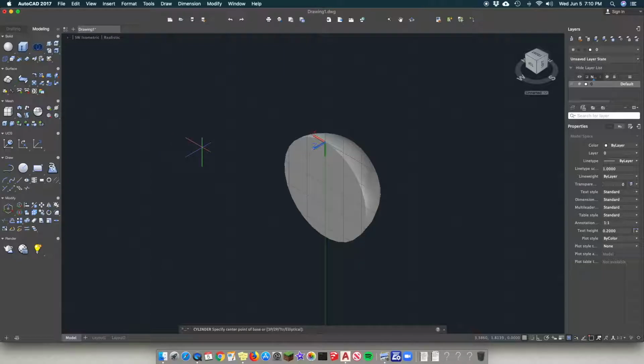Here's something you may not have noticed about how the center of a circle works. Sometimes you're trying to find the center here, and sometimes it just lights up, but if you hover over the edge of the circle, it's kind of weird, that's where the plus sign for that center point will show up. Now be careful because there's a couple of different ones that are really close together, so make sure you're getting the one that's on this outside edge. Okay, so I click there.